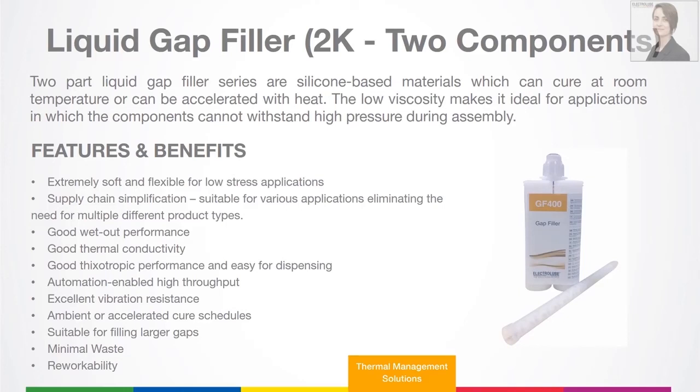They're thixotropic, so they dispense easily, but they stay in the place that you put them. And because they're curing products, they have excellent vibration resistance, and you have minimal waste. You can just apply them where you want them to go, dispensing a calculated amount, and that's it. It will cure, you're finished, you can move on to the next stage.